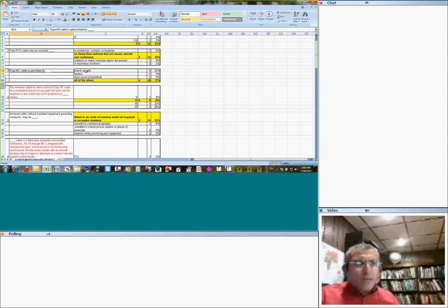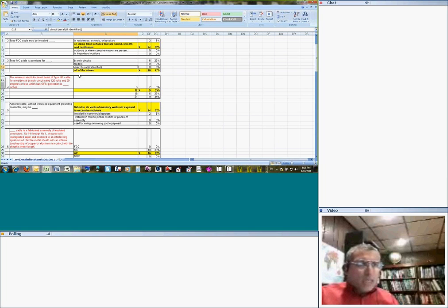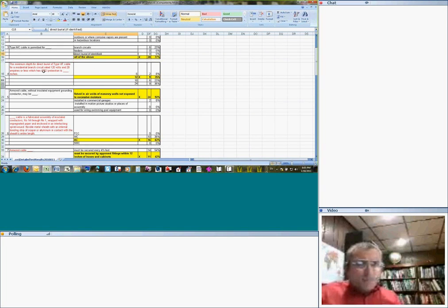MC cable is permitted to be... This is the king of the kings in terms of cables, guys. MC cable, you can use it as a surface, as a branch circuit, as a feeder, direct buried. Believe it or not, MC cable, if it has a jacket approved for direct burial, you can use it direct buried. So that's probably one of the things that maybe confused you. But if it's approved, which some of them are, you can do that.